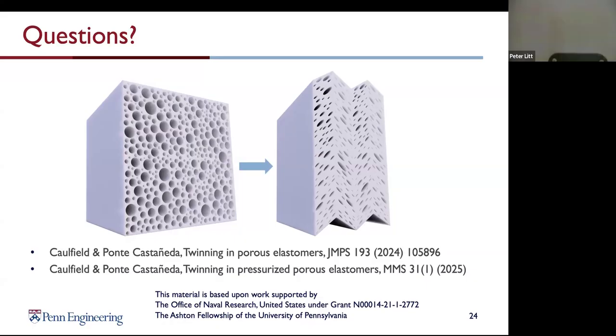In fact, this is an approach that some people use for doing random homogenization: treat it like a periodic material where you have a unit cell that is kind of disordered. Maybe approximately it behaves like a random thing, but where you can use the periodic homogenization technique. So maybe you do FEA on this unit cell that looks random and then assume the results would apply to your whole random microstructure.